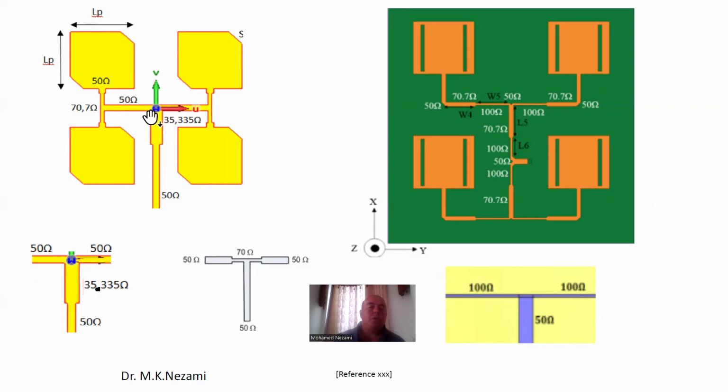Okay, so let's look in here, like this one here, for instance, the first split, we come in from 50, and we split 50 on both sides using this type here. So we got a 35 ohm that takes you from 50 to 250 ohm line in parallel. Now we got 50 in here, we got 50 in there. We can't split equally to them without using this one here. So we get this one and we use it there and we're done.